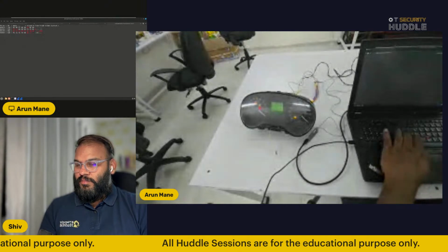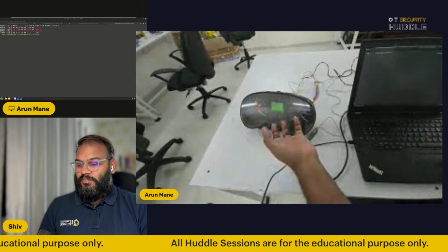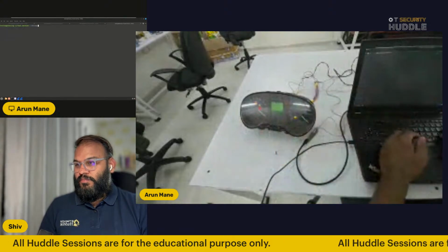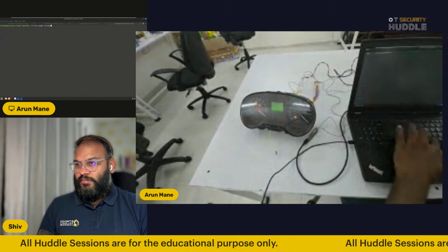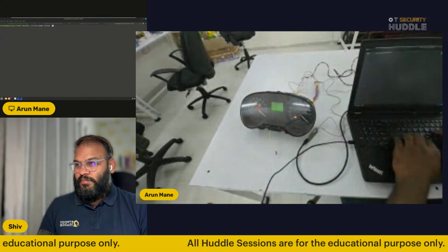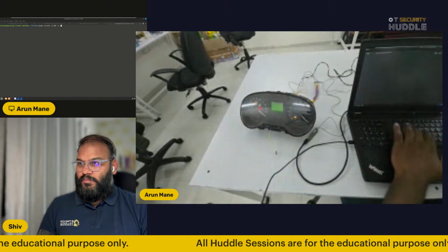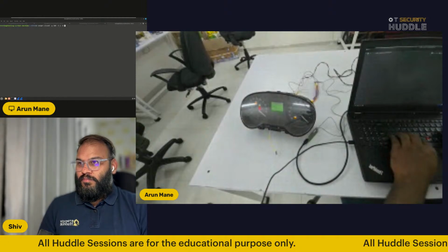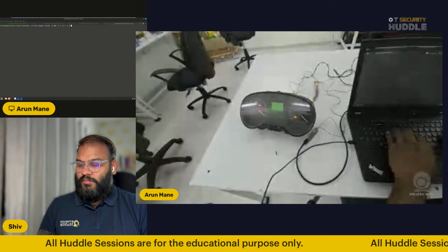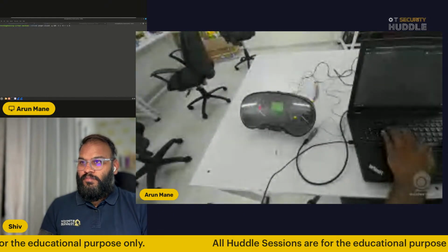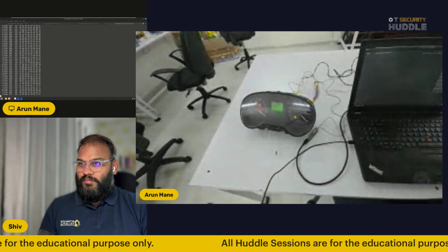But honestly, we don't know the simulator. We don't have a simulator over here, right? They give just only the instrument cluster. So how can we perform fuzzing over here? This is the last demo we are going to do. cangen SLCAN 0, hyphen g with 100 milliseconds, hyphen capital I for an incremental ID, hyphen D for random data, and hyphen capital L, where we are mentioning the 8 bytes over here, and hyphen v. So let's see, save, so you can see the changes.